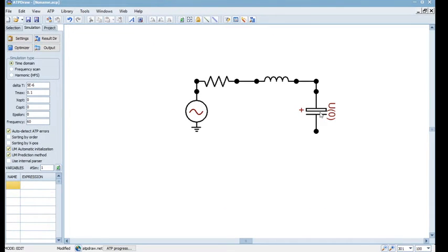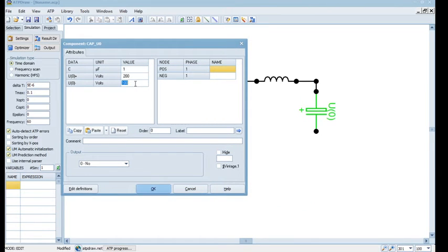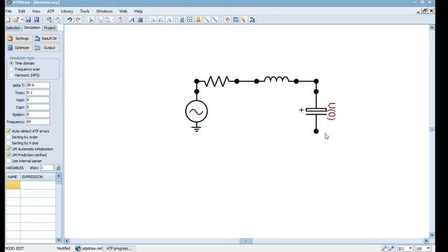See, here we have a feature of inputting the plus and minus potentials. Actually, you can specify with respect to some arbitrary value, but here we'll fix it: we'll make the negative terminal 0, and here you can specify 3 volts. In fact, you can do this also: write 0 here and minus 3 volt. Both will correspond to the same thing. So we are doing this, and this is 10 microfarad, and I will say okay. So the settings are done, but still the circuit is not complete.